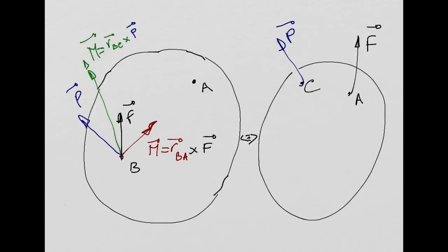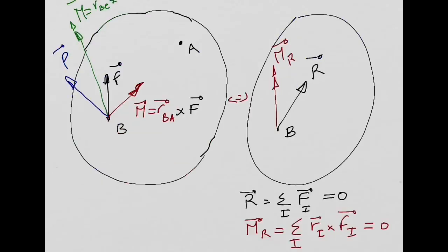The situation is we will have a complex structure with a complex geometry and many forces applied at many different points. How do we study the equilibrium of that structure? Before we start writing the equilibrium equations, we need to build an equivalent force-moment system. How do we do that? We take advantage of the moment produced by a couple. The moment produced by a couple allows me to transfer a force from one point to another by adding a moment. So I can do that for as many forces as I have in my structure. At the end, I will have everything concentrated in one single point of my structure. This point can be any point you want, chosen for convenience.